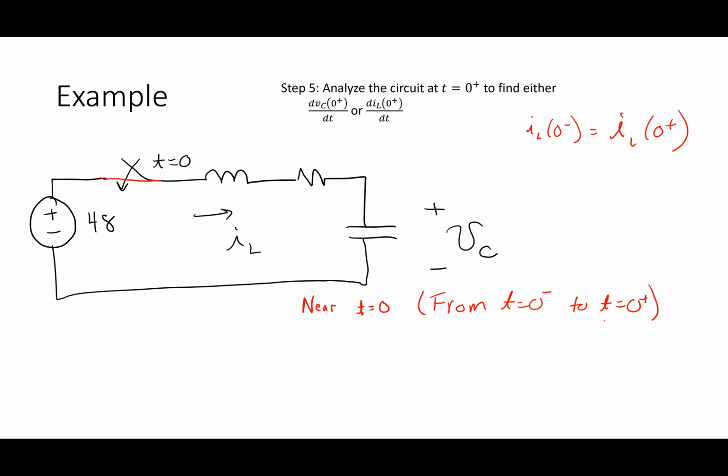In steady state, we think of it as a wire, because at that point the voltage across it has become equal to 0. In this case, not as just a wire, but as a current source. It has a fixed current equal to a particular value, in this case 0.1 amps, and I've defined it to have the polarity that's drawn right there.